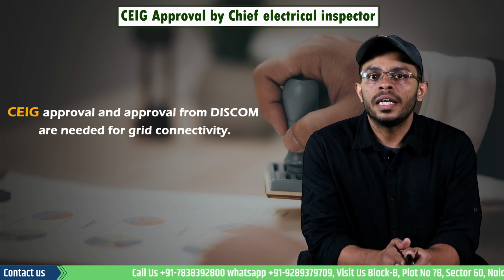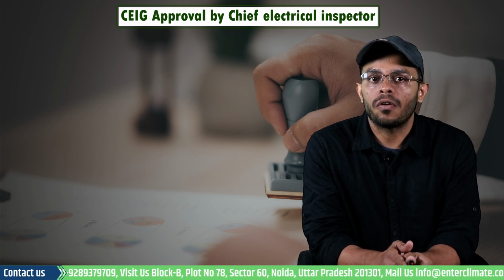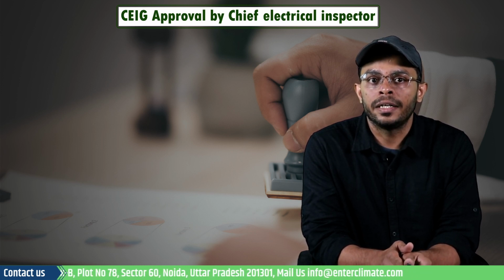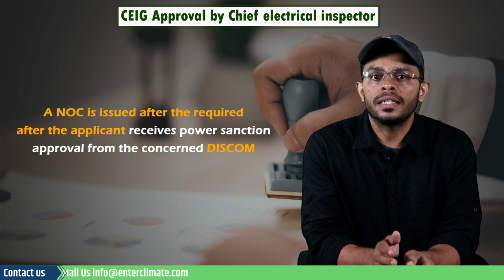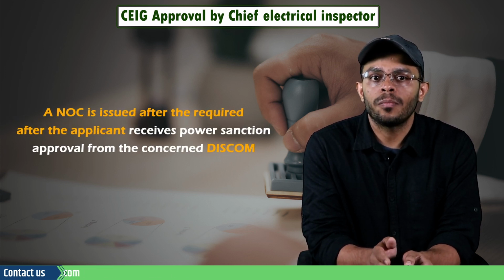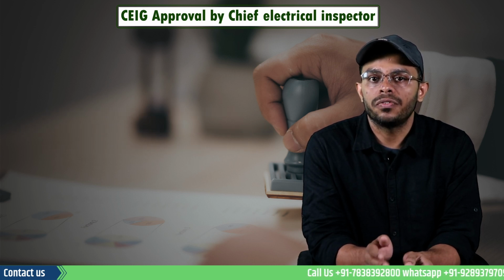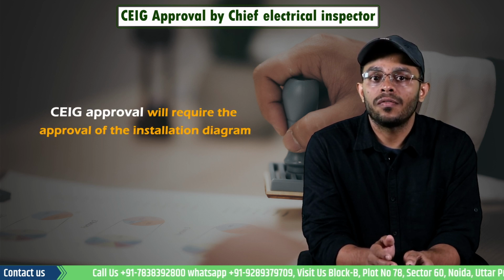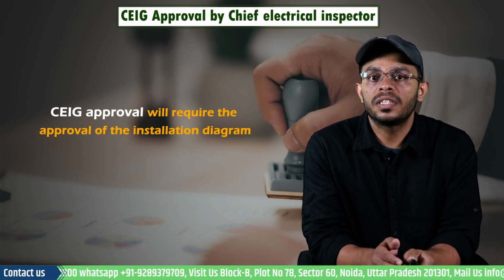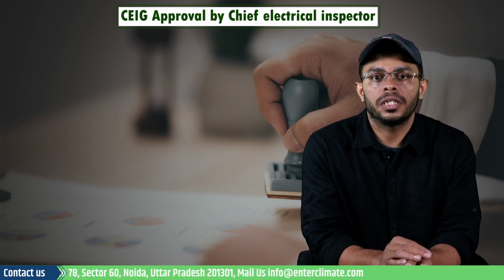The owner of the electrical installation is required to apply to the concerned jurisdictional office of the Electrical Inspectorate to obtain this approval. An NOC is issued after the applicant receives the power sanction approval from the concerned DISCOM and before the commencement of electrical installation works. After that, the CEIG approval will require the approval of the installation diagram, which will be submitted along with the relevant documents before the application for inspection.